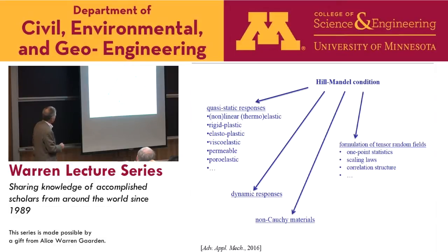And this serves as a formulation of what I mentioned in the beginning, formulation of tensor-valued random fields, which should provide input into, say, stochastic PDEs or stochastic finite element methods. And the latter ones are typically based on the assumption, well, let's take the global stiffness matrix as mean plus some fluctuation K prime. And postulates of this type, or let's just randomize Young's modulus throughout the domain. And I submit that one should do those things from a micromechanics point of view.